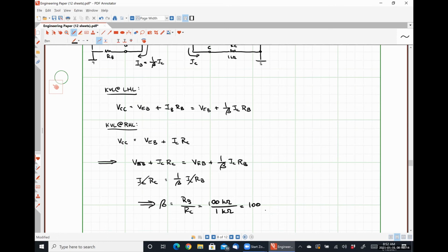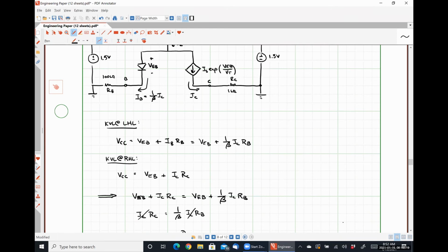But to me, the hardest part was realizing the voltage drop over the dependent current source. We've had it drilled into our heads through so much simple circuit analysis that the voltage drop over a current source isn't related to the current flowing through the current source, really. We had an alternate route here because we know that we're on the edge of saturation.